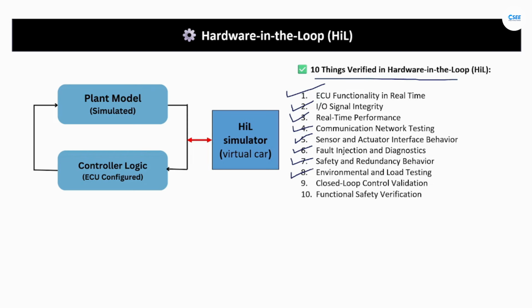Environmental and load testing, emulating temperature effects, power supply variations, and sensor drift. Closed loop control validation, confirming that the ECU maintains stability, response, and performance in simulated vehicle conditions. Functional safety verification, ensuring compliance with the ISO 26262 safety standard through repeatable, traceable tests.